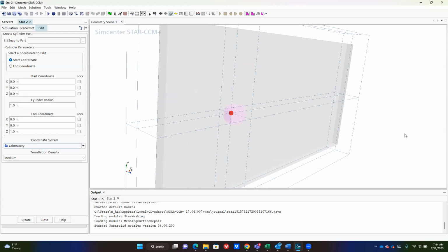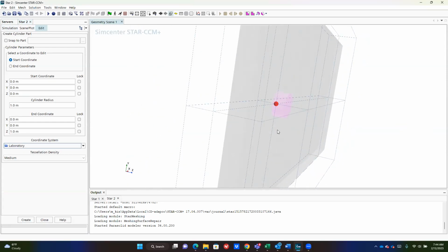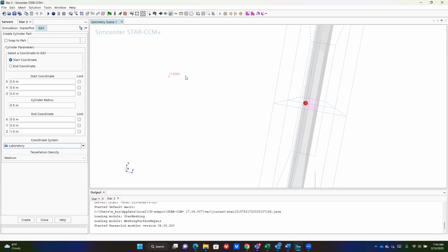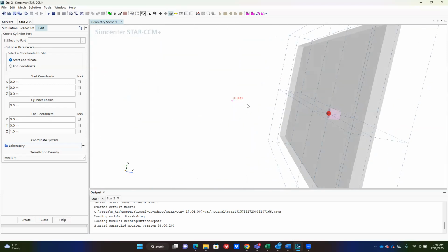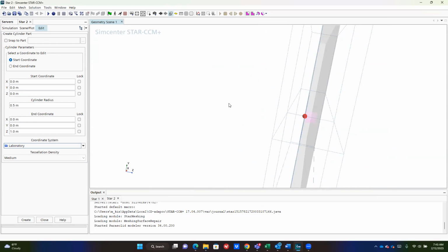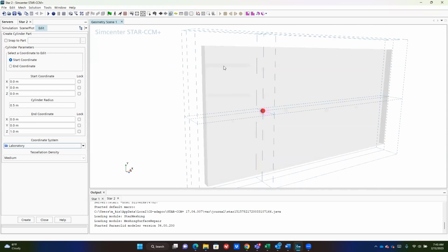I'm going to add it right at the origin, and it's going to have a diameter of 1, so the radius is 0.5. One thing that's important here is I'm going to run this in 2 dimensions, so I need to make sure that I can get a plane that falls on z = 0. The other thing is, at least in this approach, you can think of this as a cookie cutter.